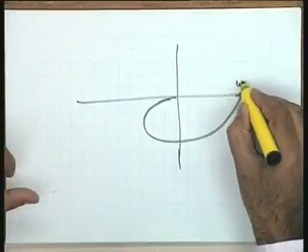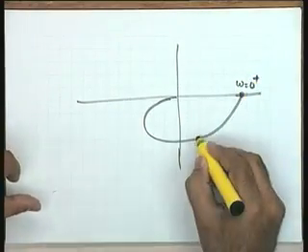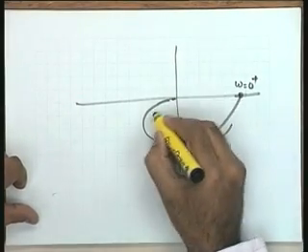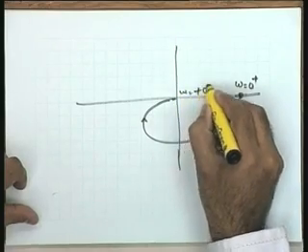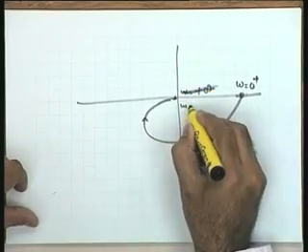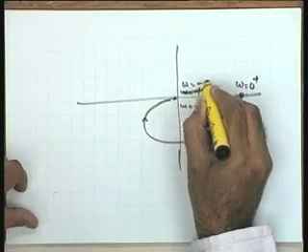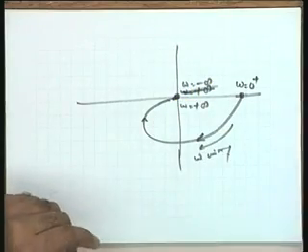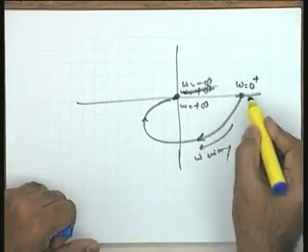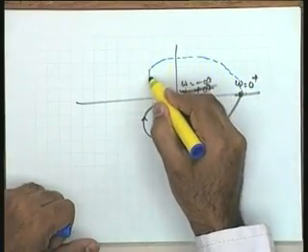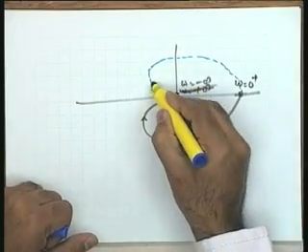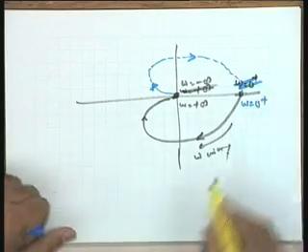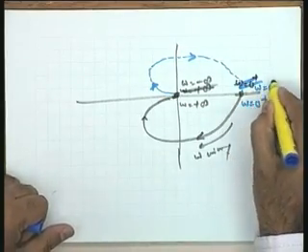So now the total plot becomes omega equal to 0 plus here, go in this direction. Let me say omega increasing, and I now take omega equal to plus infinity. On this side let me write omega equal to plus infinity, on this side let me write omega equal to minus infinity, and I am at the same point. Okay? Make a mirror image. Omega equal to minus infinity, you are going this way. Omega equal to 0 plus also should have been taken on this side. This is omega equal to 0 minus.